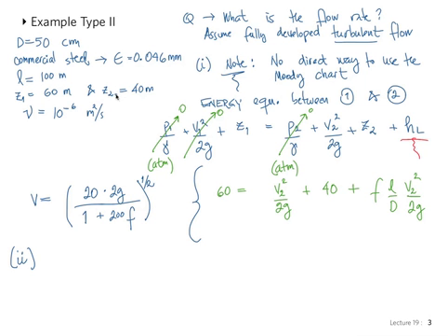I was trying to tell you the answer and nobody got it. Take a guess. So that's what we do. We guess, and with that guess, get the velocity, then get the Reynolds number, put it in the Moody chart, get f, and if it's not correct, we guess again. We do it again. That's the way. Let's try.